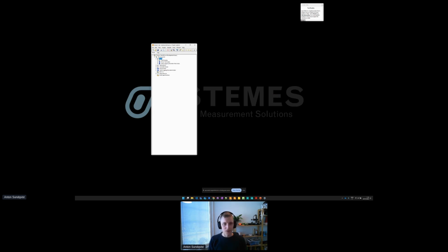Yeah, so let's have a quick look here. The scenario I'm considering here is that I have some kind of instrument talking over a serial interface. So it's basically something that uses NI VISA in the lower levels to communicate with an instrument. And I start by declaring a test case here. As I mentioned, we write the test first. And now I start with this first test, and I want to check that when I read the instrument.